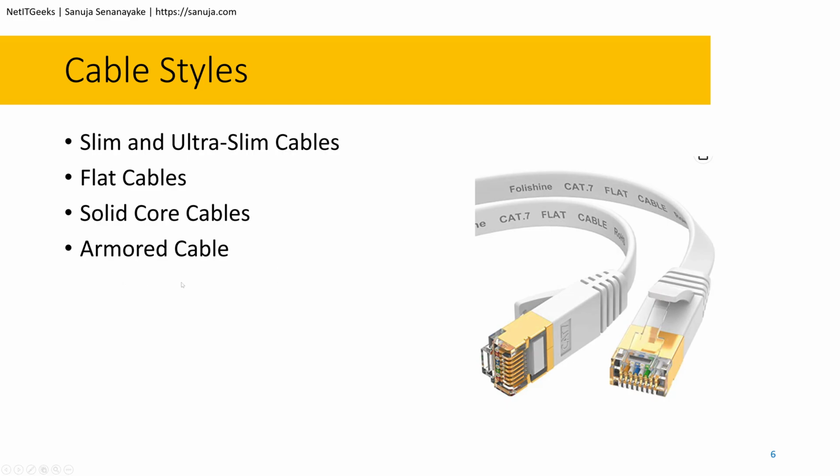And the next one is the armored cable. So the armored cables have an outer jacket that is armored to basically resist environmental conditions, as well as to provide some protection from other factors, including environments where you may need to put a cable where it may be exposed to extreme factors. So these are applications where the location potentially involves crushing or bending of your cable.